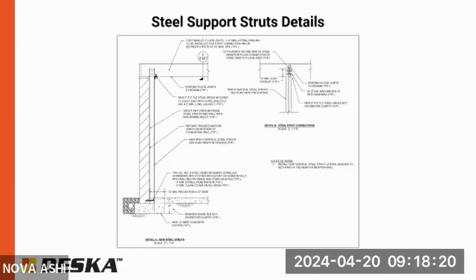If the wall is sheared at all, you really want to have these steel beams. They're more expensive than the carbon fiber straps. So ideally, carbon fiber is recommended unless you can't use it. So if the wall is sheared, you'd want to use these, and they're designed to be able to withstand that shear force.